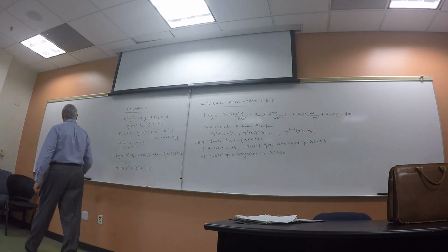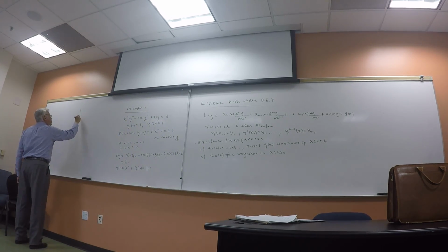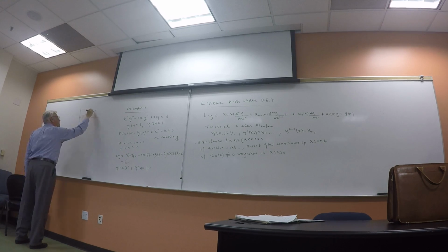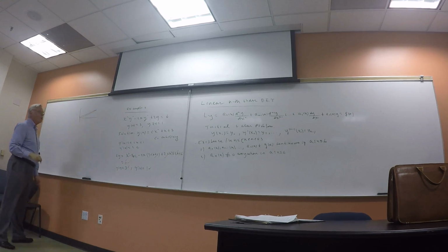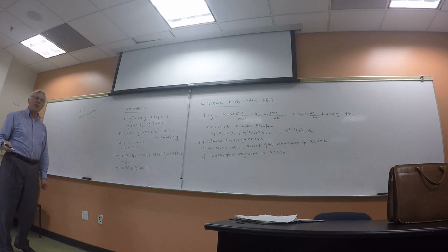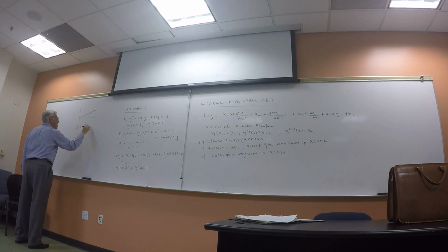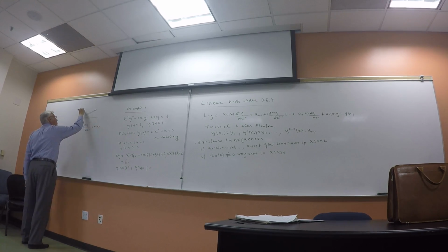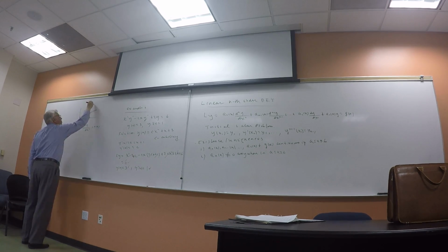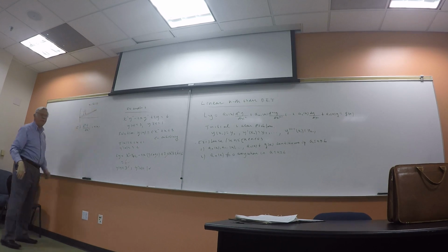So let me give you an example. This is what you'll see when you take courses on beams, plates and beams. This is supposed to be the neutral axis of the beam. Let's say it's a thin beam. There's an equation that describes the static deflection of that under applied loading. And it's basically the following. It's EI times the fourth derivative of y with respect to x is equal to W of x, where W of x is the loading per unit length. So W would be pounds per foot or something like that. It's a distributed loading on beams of external forces.